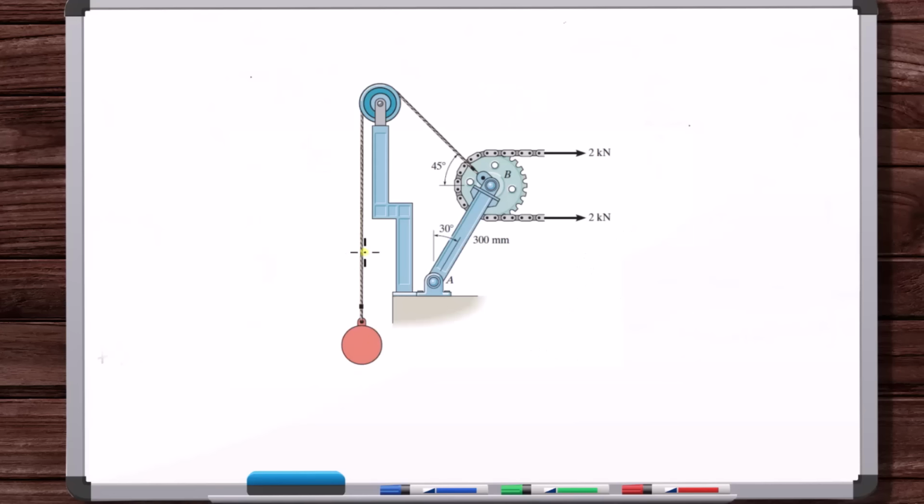If you make a slice in the rope here or a slice in the chain, these are reactions. Those are like connections, right? They're connections where you have a degree of freedom to swing the ball, but the force is in line with the rope. You're removing a connection here. Those are reaction forces. The load on the shaft of an engine, that's not a connection. That's an external force.